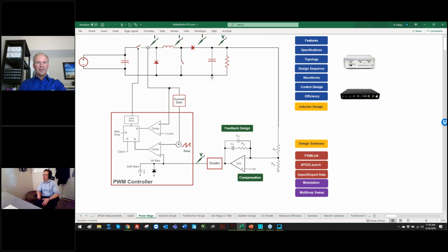So, but it also can give you false results as well. Well, to say that you can't, you actually can, if you have an open loop buck converter and it's a very high Q circuit, it's going to bounce around. Yeah. But you can sweep that even with the bouncing around, and if your sampling is enough and your bandwidth is okay, yes, you can get some numbers from it.